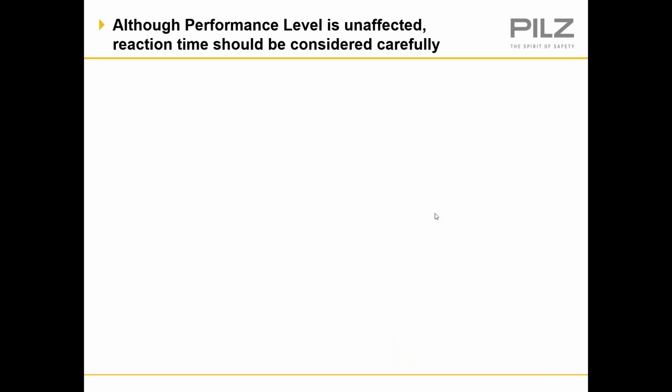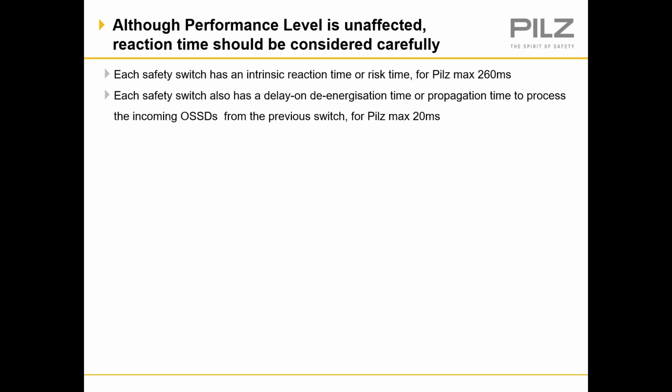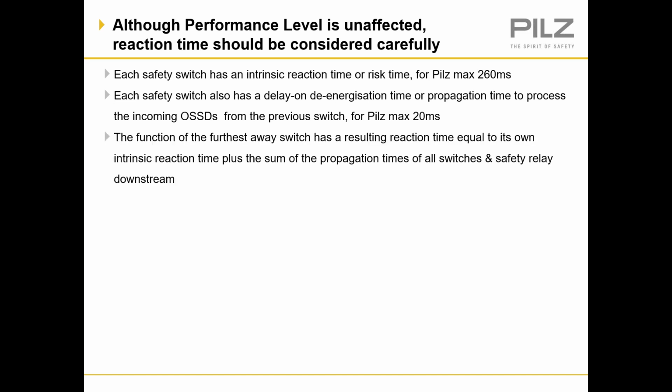So although performance level is unaffected, reaction time should be considered carefully when using these devices. Each safety switch has an intrinsic reaction time or risk time, and for Pilz, our maximum is 260 milliseconds. Each safety switch also has a delay on de-energization time, or propagation time, to process the incoming OSSDs from the previous switch, and for Pilz, that's 20 milliseconds.